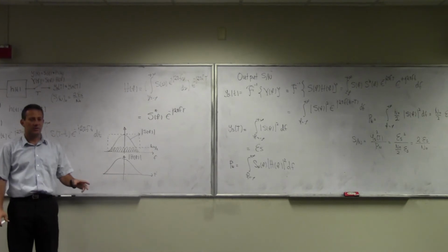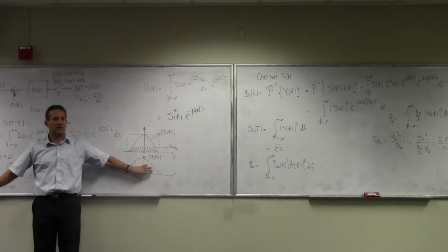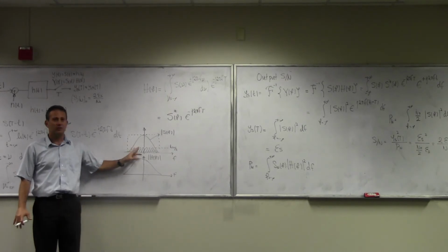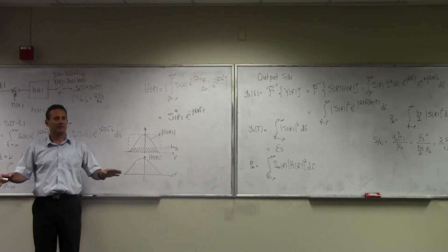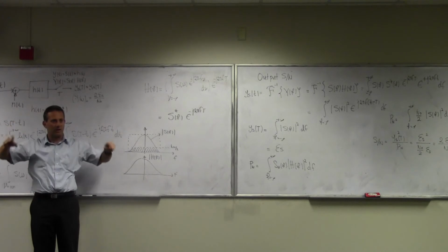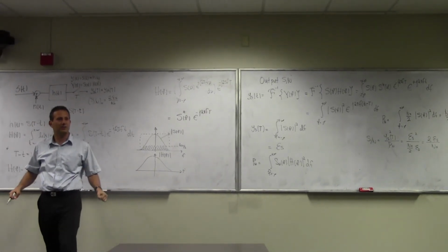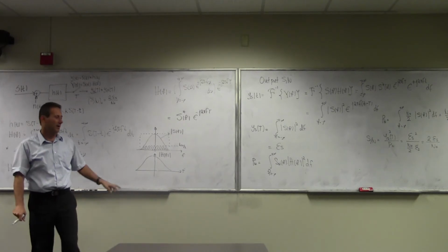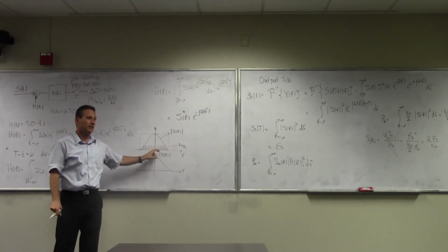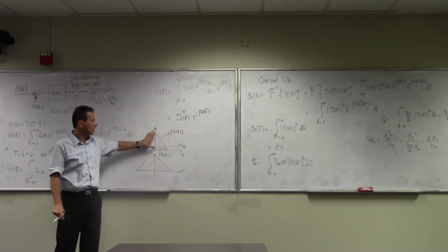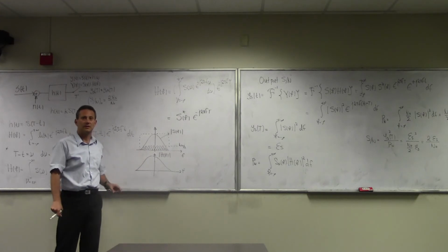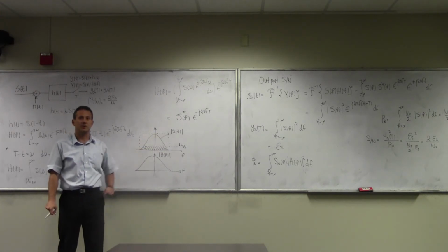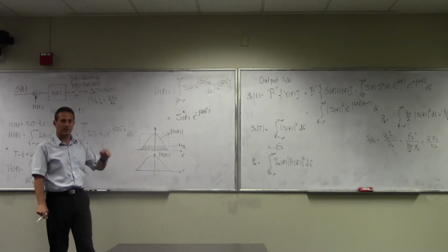So the way you can think of this is you have a filter, you have a signal, it's shaped somehow in the frequency domain. You're making a door that this signal goes through. You're fitting the door right to the signal, right? So wherever the signal is tall, the door has the exact shape of the signal. So the signal just squeezes through this door, right? And the noise also squeezes, right? But the portions where the signal to noise ratio is high, those are really amplified by the filter. These guys are attenuated, and then these are eliminated. So this door is really tailor-made to this particular signal. That's why it maximizes signal to noise ratio.